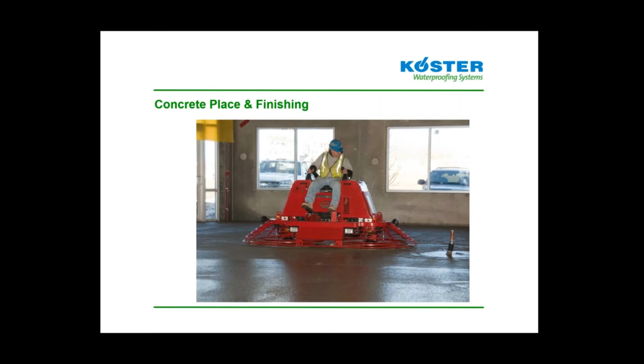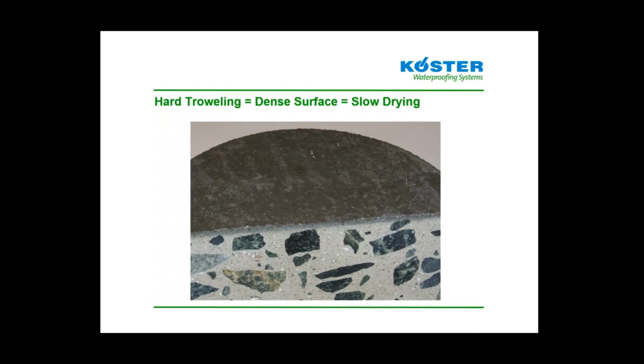These ride-on trowel machines can weigh over 3,000 pounds and put a lot of pressure onto the floor, extremely consolidating the top surface of the concrete, as we can see in this picture. This photograph is of a concrete core cut from a dense power-troweled floor. The dark surface is almost stained, as it appears to be like a dry shake or a stain treatment. This region of approximately the top 1/8 inch of the concrete is due to what we call compression dewatering. That high-pressure troweling densifies the cement paste at the top surface. Water is driven out of this zone while it is consolidated and densified.